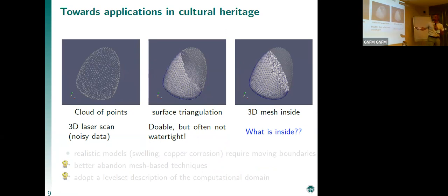But if you build a surface triangulation for visualization purposes, you don't have quality requirements on the triangulations like those that we have for the numerical computations. If you look at this triangulation, you will notice that most of the triangles are close to equilateral. And if the discretizations that we use are close to being regular, then the numerical methods will perform much, much better.